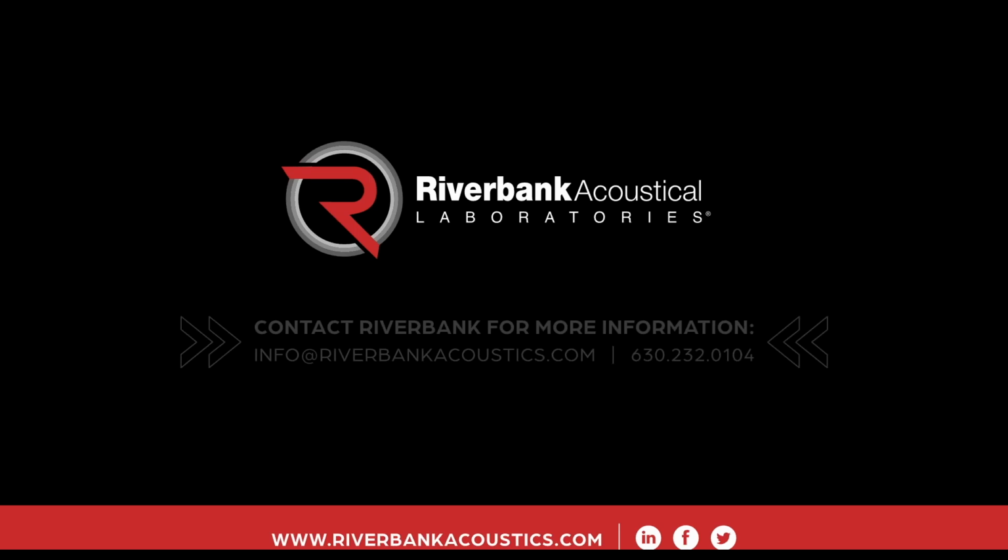All right, great. And the last question that we have here: can the NRC value be over 1.0 based on reporting methods? Yes, and it's not surprising or alarming. It's not a sign that something was done wrong. Remember, NRC is an average sound absorption coefficient, a frequency average, and sound absorption coefficients can exceed 1.0.